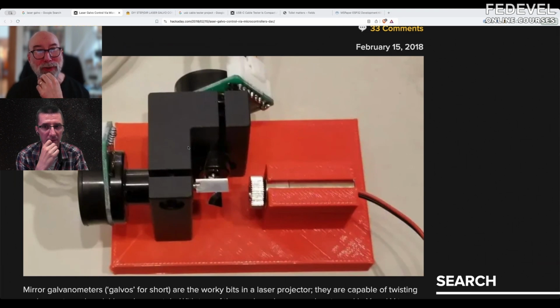It's really hard to get it to work well because if you drive it too fast, then it just overshoots and you end up with terrible lines. But if you drive it too slow, the refresh rate gets very flickery and you're drawing very slowly. So I think it's a bit of an art in tuning the parameters to draw quickly enough.